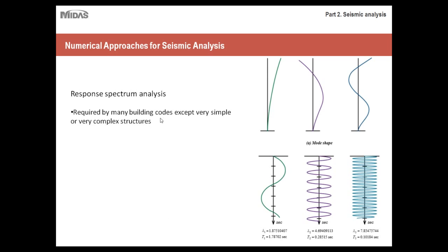If you have a structure that's very simple in a low seismic region, you use equivalent linear analysis. But if you have one that's sort of in the middle range, not a very complex structure in a very high risk region, but still in a seismic region, and it's a building that isn't low-rise, that might be a little bigger, then you would use response spectrum analysis. It's sort of in the middle, and because of that, it's the most widely used.